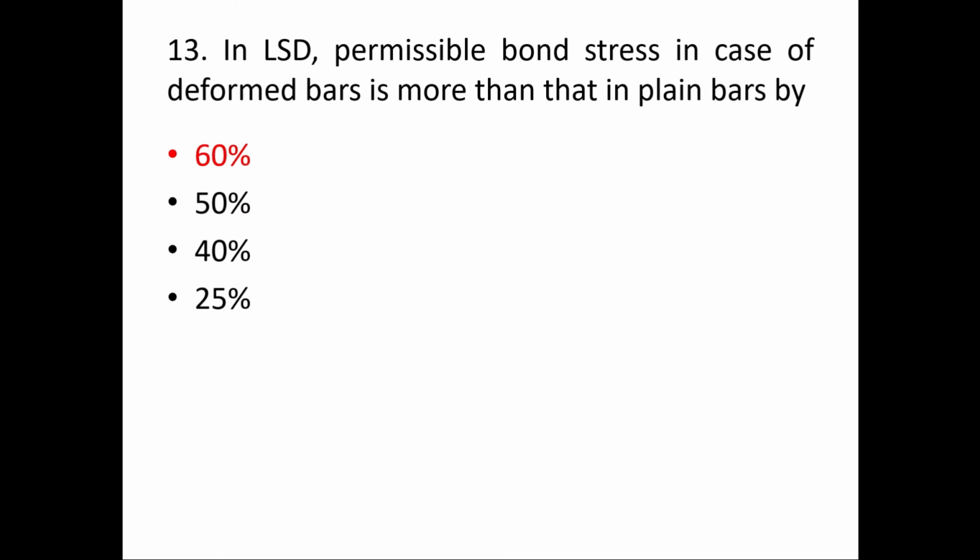In limit state method of design, the permissible bond stress in case of deformed bars is more than that in plain bars by 60%. So this is our important question. As for deformed bars, the bond stress shall be increased by 60%, we know, over the values of plain bars in tension. Okay, and for the bars in compression, the values of bond stress for bars in tension shall be increased by 25%.